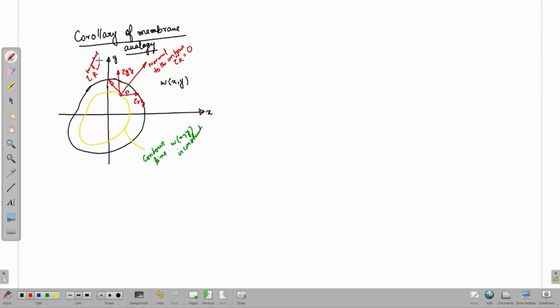Suppose I need to find the shear stress at a point on the cross section of the shaft, then I have to imagine a contour line through the point. Then I can say that the resultant or the total shear stress at the point is only in the direction of the tangent of the contour, and the resultant in the other perpendicular direction is 0. This knowledge is very beneficial, as we will see later when we solve examples.